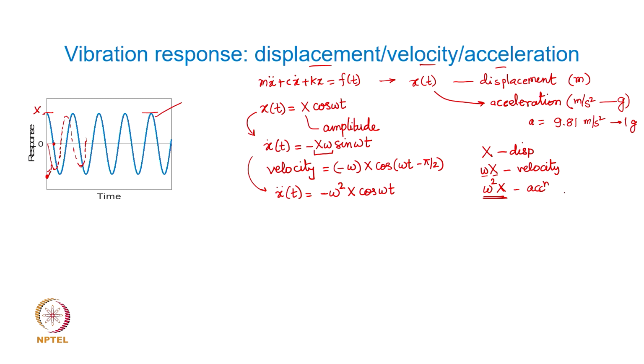Okay. The units of velocity response are obviously going to be the standard units, meters per second, but in practice the velocity based measurements are typically recorded in the units of millimeter per second. The displacement can have any unit as such, but many times for small levels of vibrations, micrometer is the displacement unit, because typical mechanical vibrations will not go beyond a millimeter value.